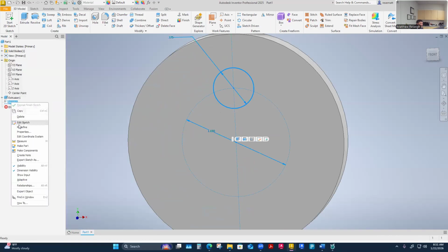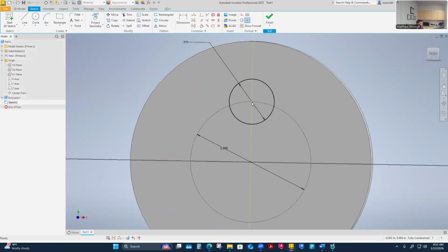If I was in there, I'm going to go back in to edit this sketch here. Mine, that is that constraint. I would just delete that one. So if it didn't automatically constrain, then you have your option to constrain it however you want. Mine would probably be another coincident constraint. I'd probably use that and the circle and then to this. If I had drawn in this construction circle, I would probably use a coincident constraint to the center of my circle and then to this, and that will pull it together.